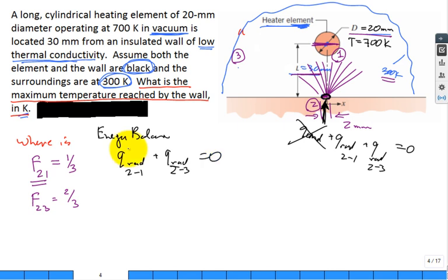Okay, what's my equation for the radiative exchange going from 2 to 1? Well, it's as easy as A2 F2-1 sigma (T2^4 minus T1^4). Does that look familiar? We could use the resistor concept, but this time it may just slow us down to put in resistors.